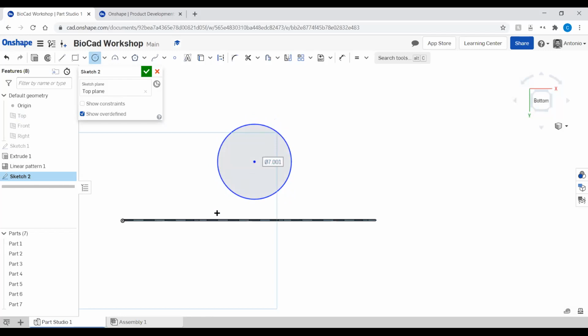Cool. So we have to do some math now, and there's a reason we had the numbers line up the way that they did. Remember that horizontally, each of those units was 2 millimeters long. So one unit was 8 millimeters because it was 4, and then we patterned that 3 times. So the total width of this guy here is 24 millimeters long. If we want to wrap it around the circle, does anyone know how big we need to make the diameter of our circle? Some geometry. Any guesses?